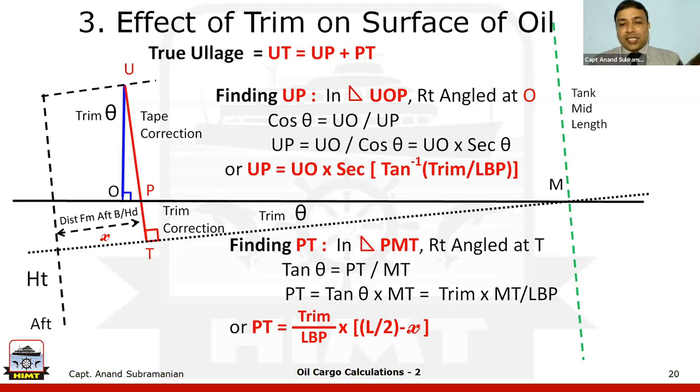What we have is just a hole on the top, and from there we hang the bob down. The sounding pipe, like what we have in the ballast tanks, will not be found in the oil tank, because they increase the shadow areas. They're difficult to clean, and what is in the shadow area of the sounding pipes can't be effectively cleaned, so it may interfere with the next cargoes. So we have just a hole on the top, and from there we put the bob down.